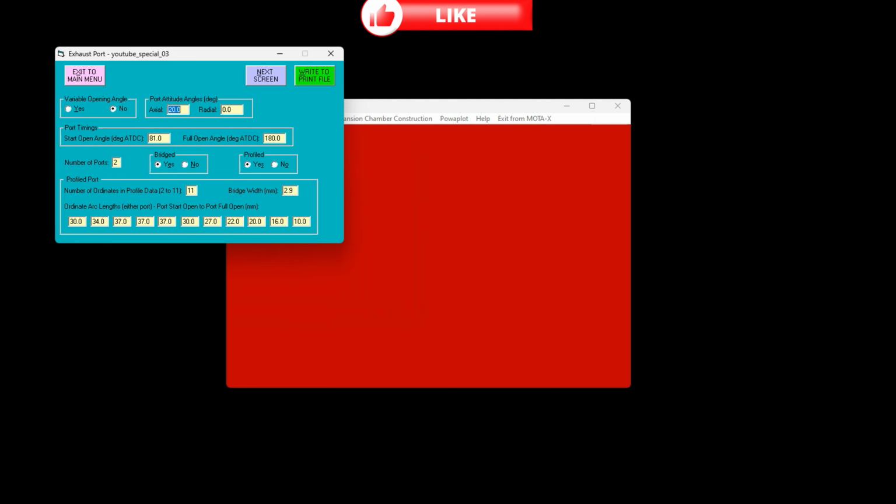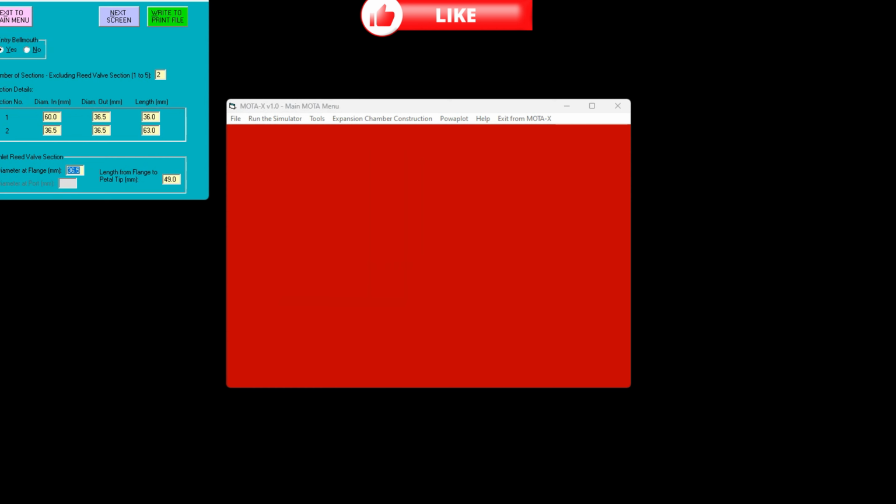And here I shaped the exhaust, and sadly enough, I can't shape main exhaust with auxiliary exhaust ports. I can only make a bridged port here, so I'll shape it like a bridge, like a main and auxiliary. But yeah, the area is almost the same, and you can set in all the transfers also some angles and how it is aimed out from the cylinder, and the transfers how it is aimed into the cylinder.